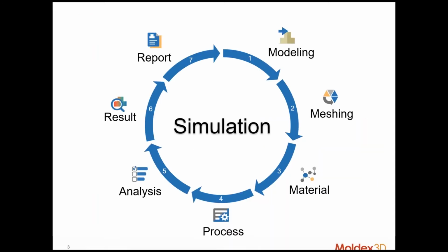So when it comes to running a simulation in Moldex3D, we have a series of steps, or a workflow, if you will, starting with bringing in a model, doing the meshing, selecting a material. You can set up different process parameters, select what kind of analysis you want to run, and then review the results and generate reports.